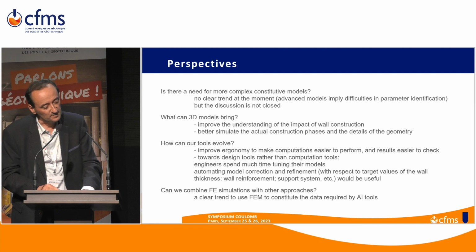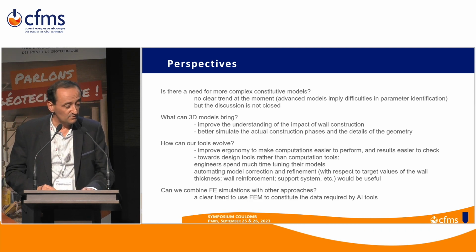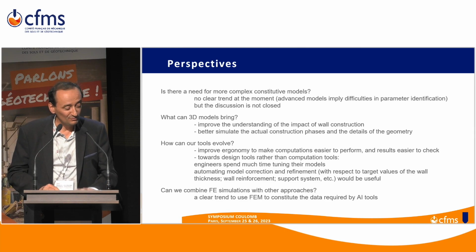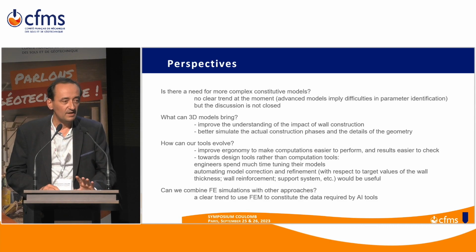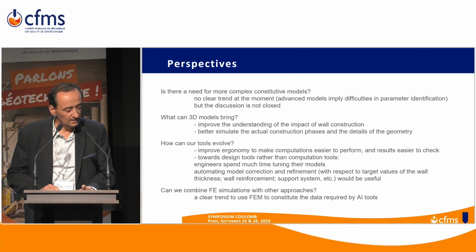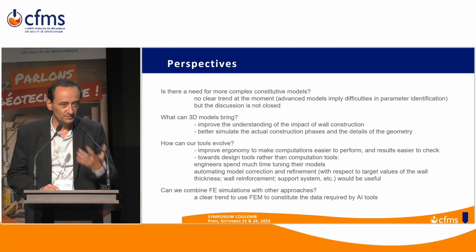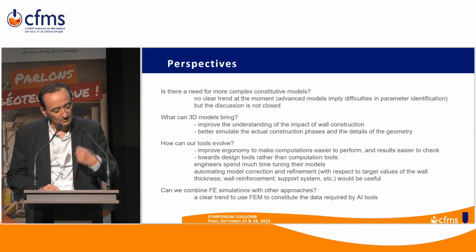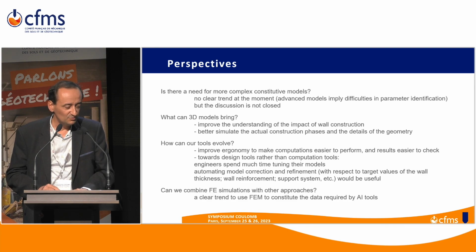Okay, so a few words of perspectives. Well, first of all, is there a need for more complex constitutive models? I'm interested in the question, so I would have liked to answer yes. But at the moment, people seem to be satisfied with typically the hardening soil model, because more advanced models would imply more difficulties in parameter identification. The discussion is not closed, because if we want to improve the prediction of the settlements, provided that we measure it, probably we will have to start a new cycle of reflection about the constitutive models.